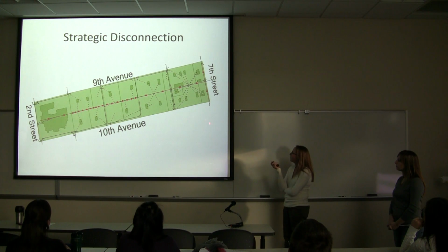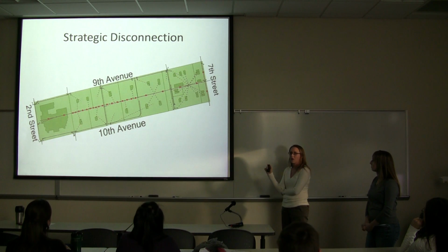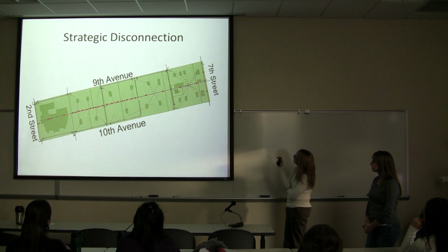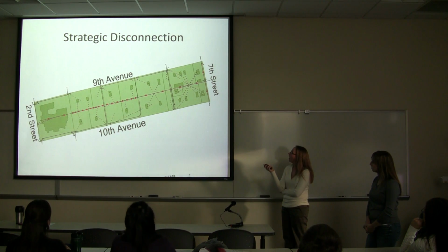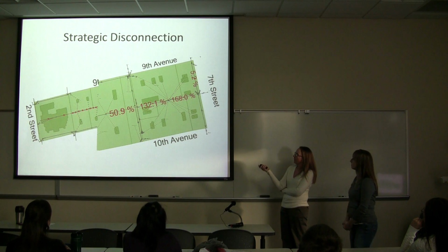So from the Google Earth data that we looked at, like she said, we thought it went to this catch basin. So we decided to say, well, what if you just block that one off? No overland flow can go into it. So everything would have to be redirected to 196 here. And in that case, we kept the 80% disconnection and just rerouted flow. And you can see here that on the 1-year storm, that produced